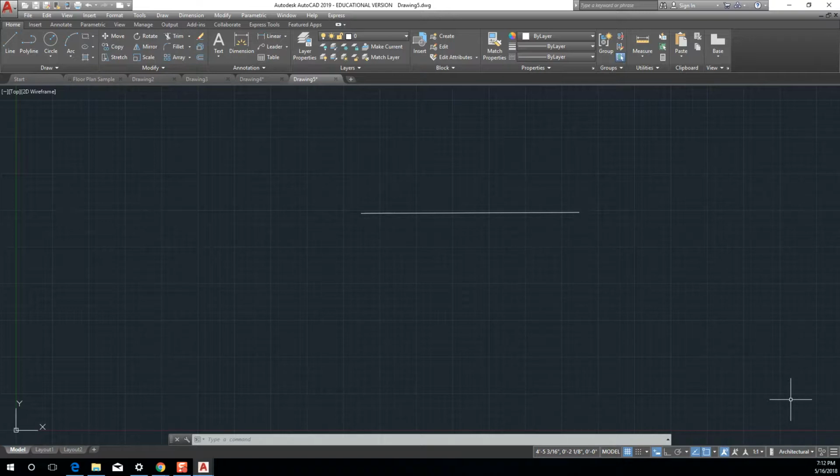So, and the same applies for anybody in construction management, right? You'll get files from both disciplines and need to know that one is 12 times too small and one is in architectural units, right? So you're going back and forth and you're drawing in both units all the time, okay? So it's important to know the difference. So we're going to be drawing in this class, well, we'll be going back and forth a lot, but when we're drawing architecture, we'll be drawing in architectural units, okay?